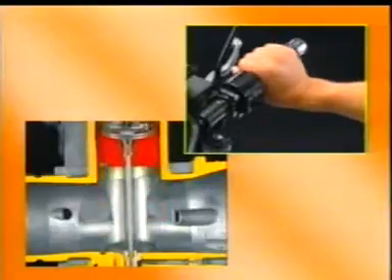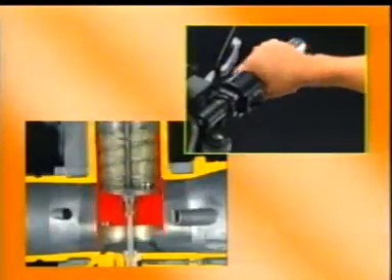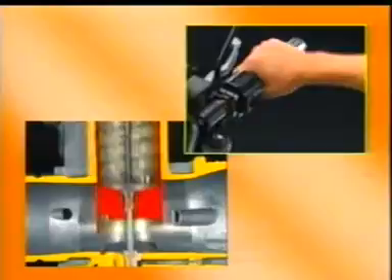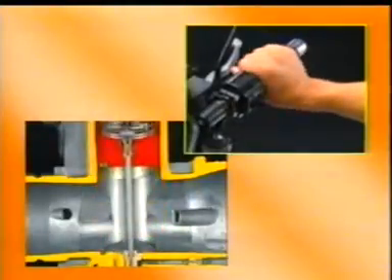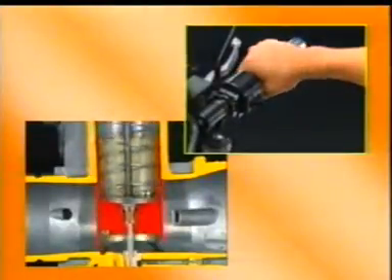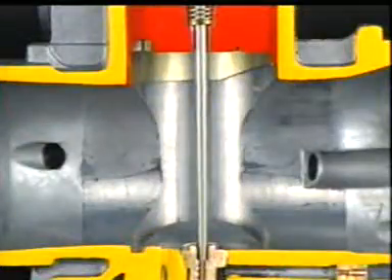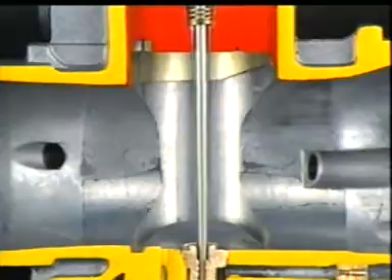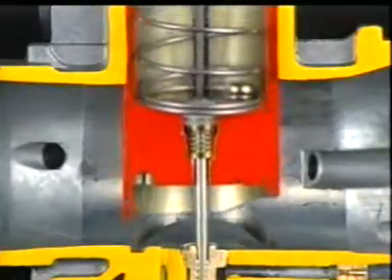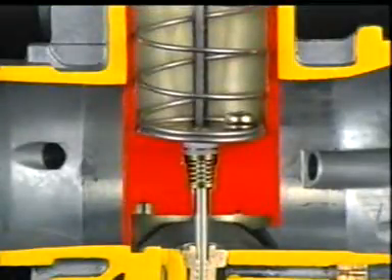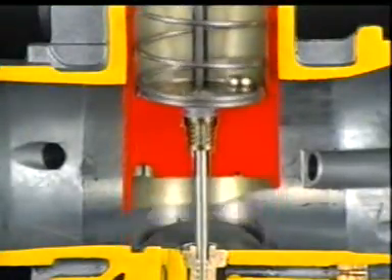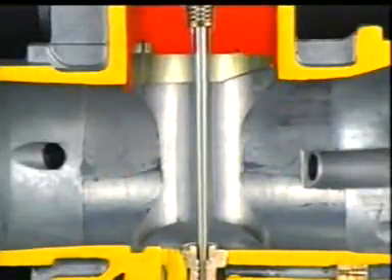At this point, the diameter of the main bore is changed by the throttle valve, so that the Venturi goes into action. The amount of air supplied to the engine is controlled by changing the position of the throttle valve. When the throttle valve is in its lowered position, less air is supplied to the engine, and when the throttle valve rises, the amount of air increases.